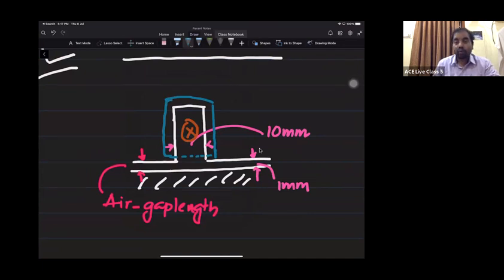it will find two ways. What is the first way? Without crossing the air gap, via the slot, it can complete the path. The other possibility is it can cross the air gap, and via the rotor core, again cross the air gap and complete the path.